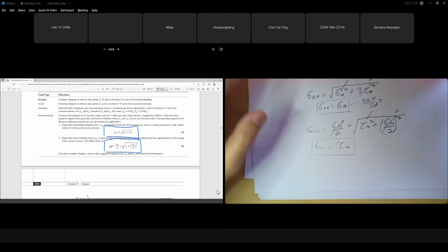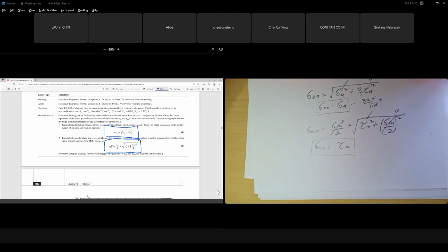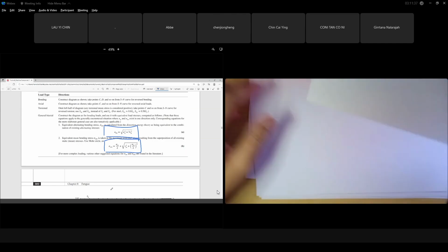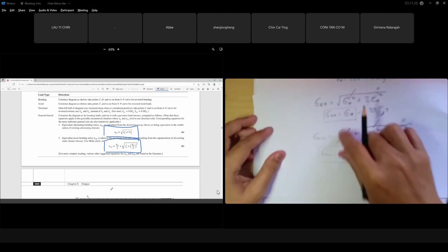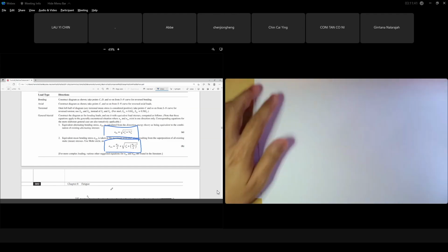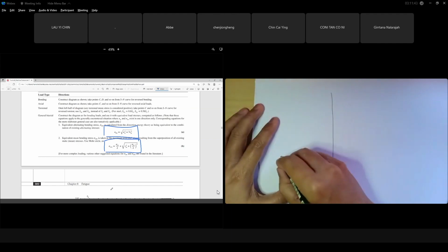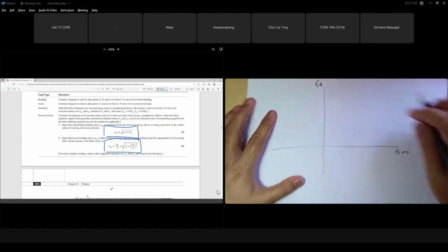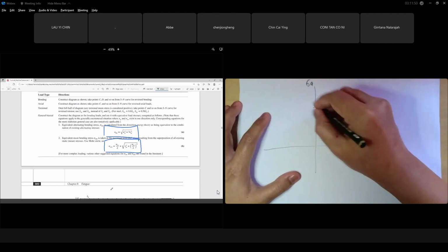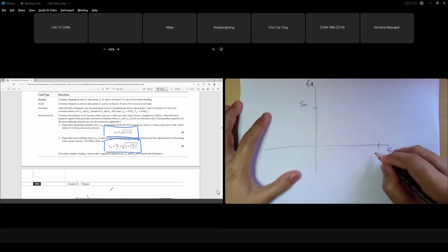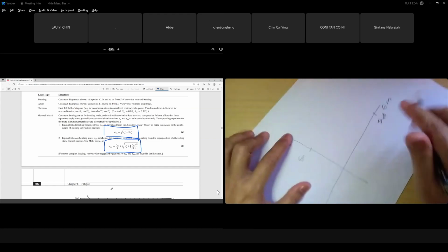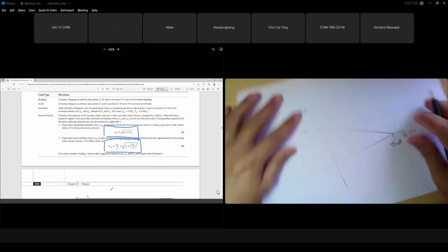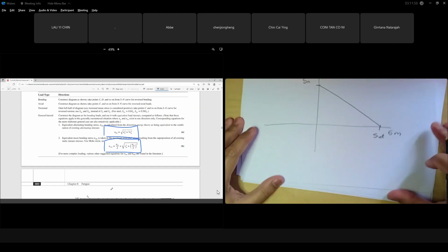Okay, then yang saya cakap you plot into this graph kan. Sorry, saya dah over. Itu yang tadi. So, you calculate your sigma EA value. Okay, this is your punya plot of your graph. Okay, yang tadi cakap sigma mean versus sigma A. Sigma A is your y-axis. So, this one your border is your Sn. This one, the border is your SUT. So when you make a straight line, it's like that. Okay, straight line like this.